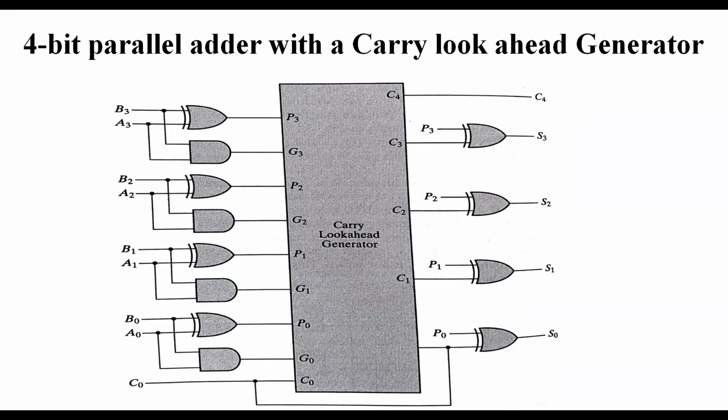By doing this, what is the advantage for us? Here, the final sums are generated without any propagation delay. When compared with the 4-bit binary adder, where the sums are generated with intermediate carries, here the sums will be directly generated as we give the inputs. There is some delay, but compared with a normal full adder, the delay is less. The speed of operation has improved somewhat. Since we designed the circuit directly for the carries, these carries will be helpful for generating the sum.